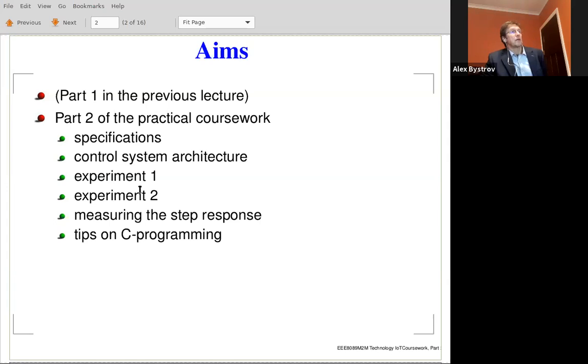This transition can be plotted, and if there is plenty of over-regulation and oscillatory behavior is observed, then it is kind of an unstable system, and if it gradually approaches the required speed and stays there, it will be stable behavior. So it is possible to measure things rather than just to chat about this. So I suggest to use the measurement. And there will be a slide later on about how to do that.